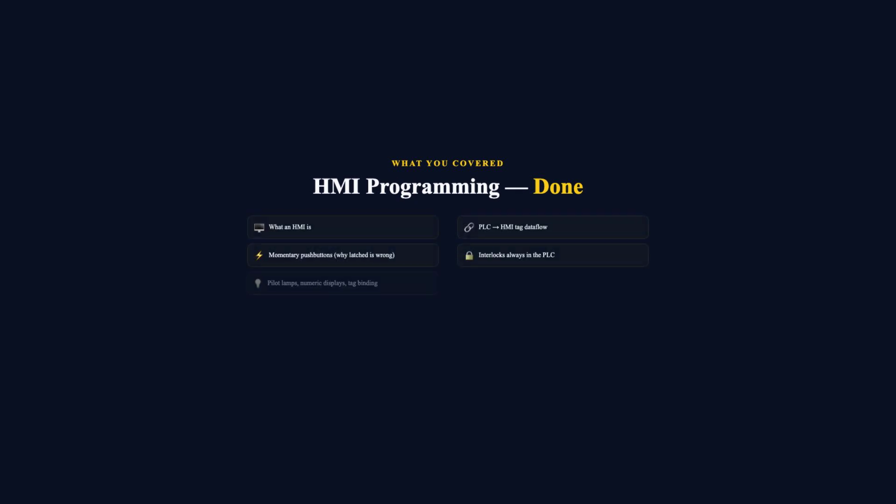What an HMI is. How it reads and writes PLC tags without doing any logic. Why momentary push buttons are correct for motor circuits. Why interlocks always live in the PLC. How pilot lamps show output state. How tag binding connects the widget to the variable. And how to build, run, and grade a real motor start-stop screen.